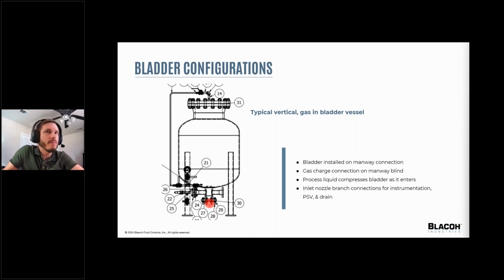In each vessel type, the liquid somehow compresses gas in the vessel, like Chris mentioned, which changes your system from incompressible to compressible, and the energy is immediately available, as opposed to a valve, like a spring-operated valve, that may not be able to immediately respond or won't immediately respond.